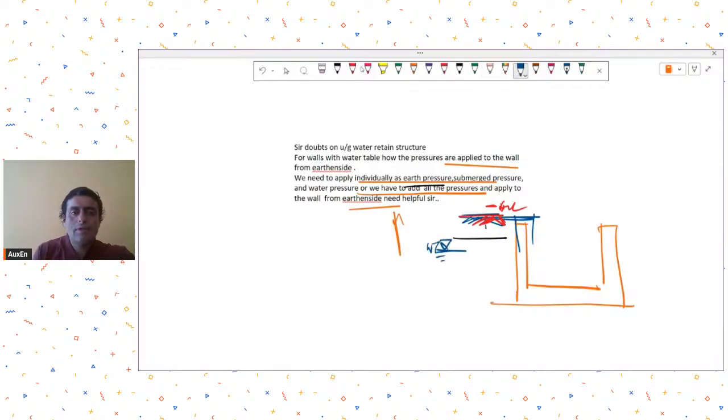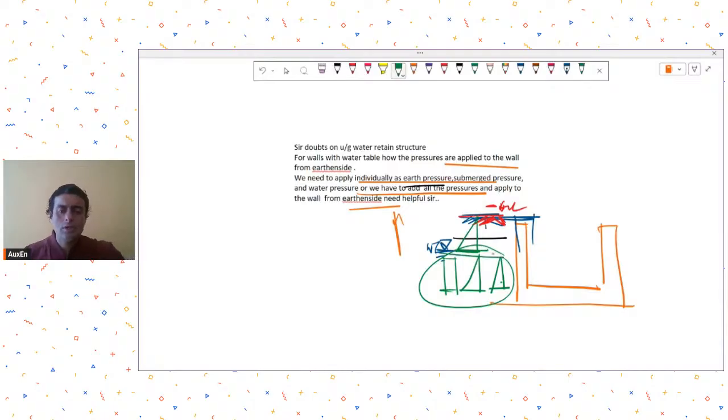So above this, you will apply your soil pressures in the normal manner, and then below this, you will have the soil pressure plus the portion of the load that gets transferred from here, plus the water pressure loads. All these will have to be added below the water table depth. So this calculation has been well explained in the course on liquid retaining structures that you have already joined. Okay. So I request you to go through those sessions. You will understand.